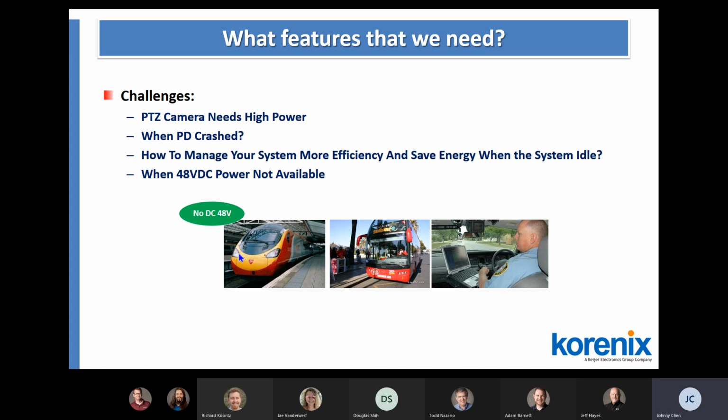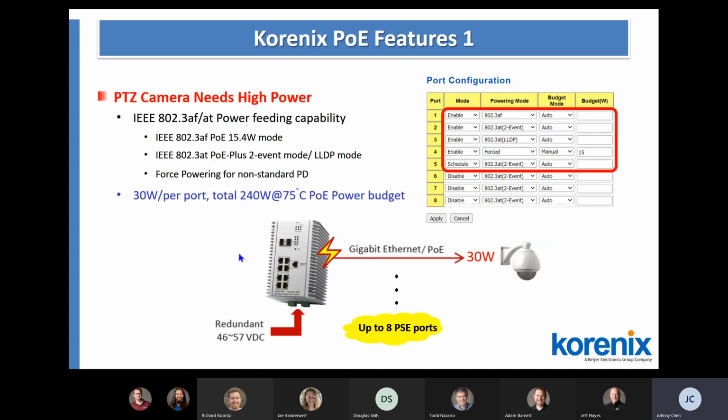Okay, so let's take a look at the first challenge, the PTZ camera needing high power. Of course, almost all of our managed switches right now support AF and AT mode, so we can provide 30 watts per port.